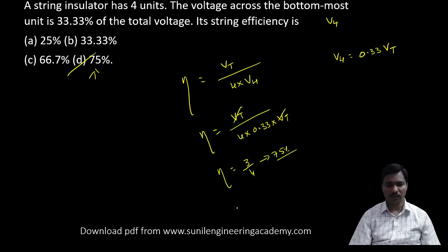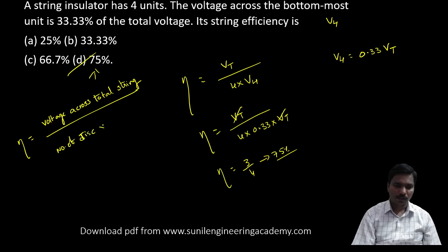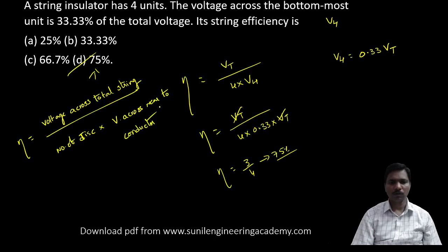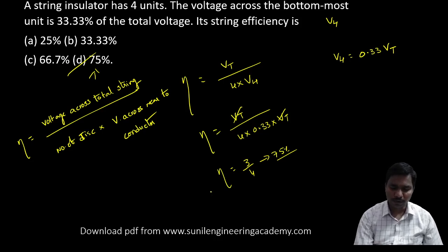So like that we can go with. Okay, so once again note down this formula: voltage across total string by number of discs into voltage across the disc near to conductor. From that formula you can easily calculate.